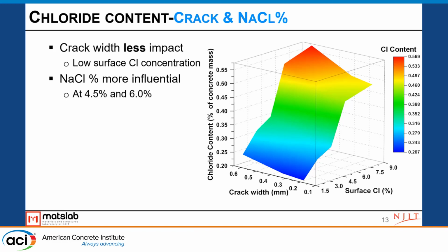And also, if we look at a specific crack width, the chloride content increases fast at the 4.5 and 6% surface conditions, which means the chloride concentration is more influential at these two concentrations compared to the others.